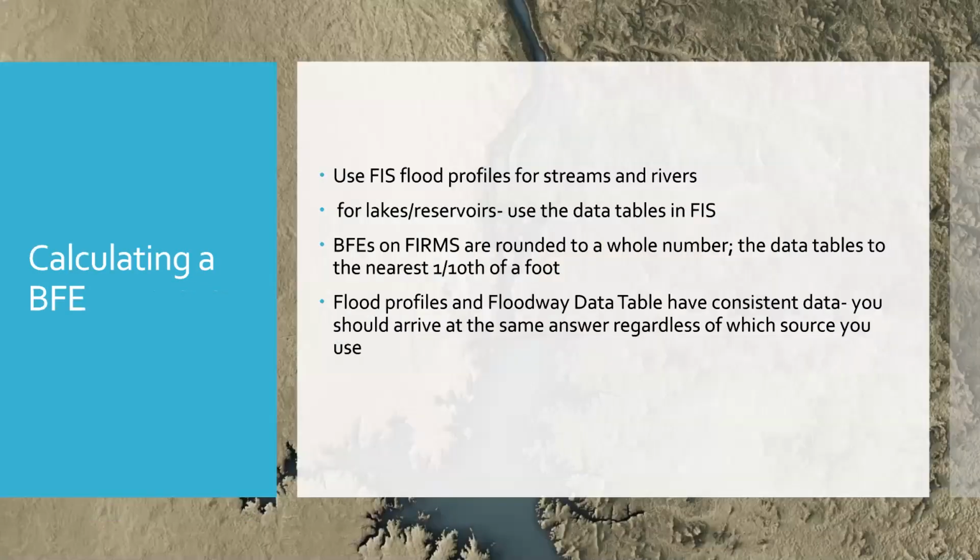So I need to check this BFE and make sure that the contractor has done it correctly. So I'm definitely going to use the flood insurance study, either floodway data tables, if that's applicable, or the flood profiles for a stream or a river. For a lake or reservoir, you want to use the still water data tables in the flood insurance study.